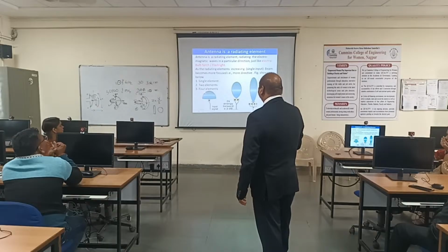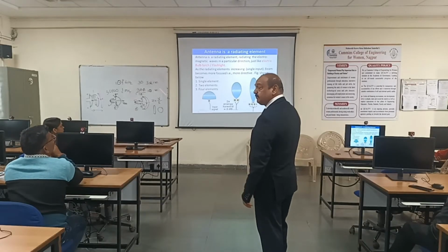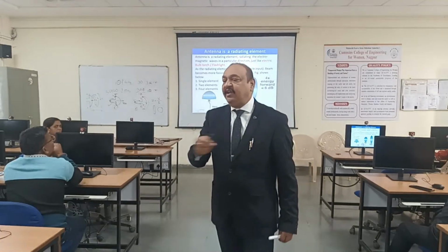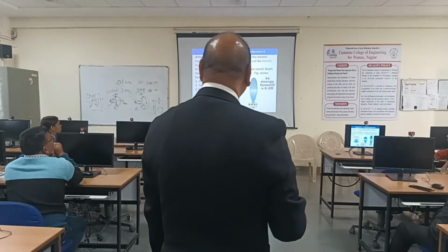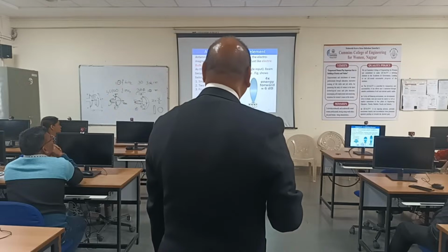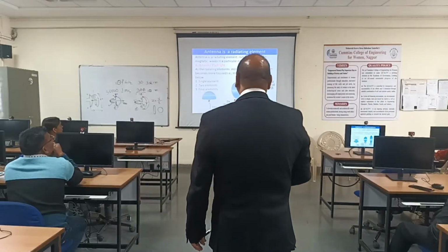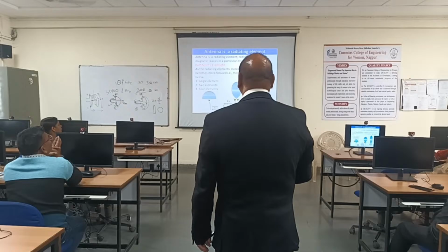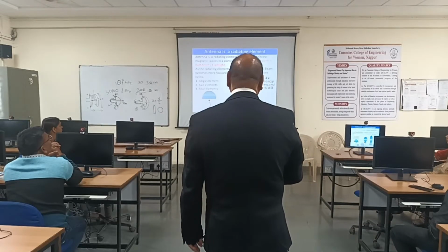See, if you just take a single element, it radiates like this, like a globe. It is simple. It's an isotropic type of antenna. It radiates equally in all directions. That is a single beam. That is the input, a single radiating element. But if you want to make a directive antenna, you have to use two elements which have to be excited by the signal source. So then the power is increased by 3 dB. Means double the gain you will get in this case.